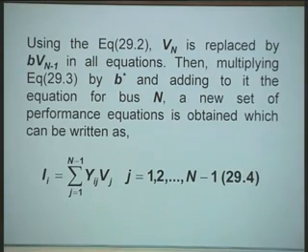Now, in case suppose you have, instead of two generators, one more generator which forms a coherent group, you can perform a similar additional operation, and you can keep on reducing the number of buses, right. And while doing this network reduction process, what is to be done is that we retain the voltage of one of the buses at the original level.